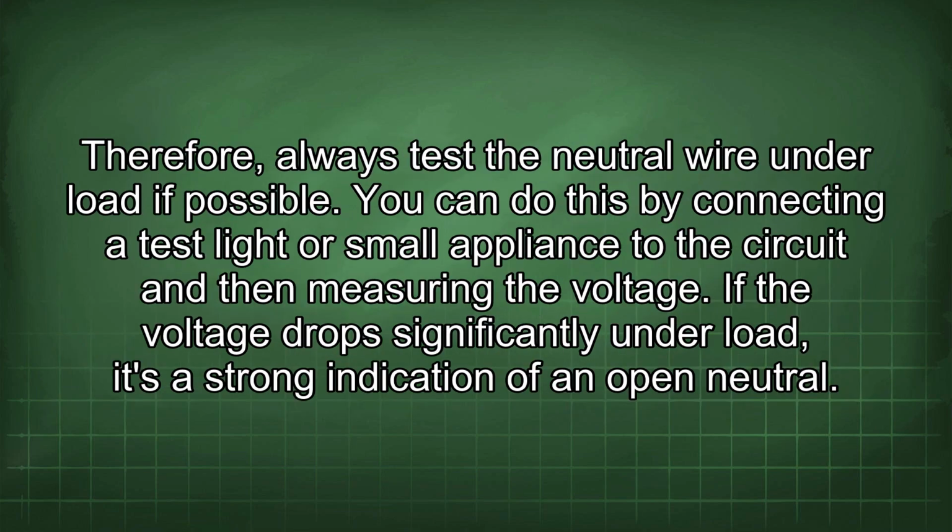Therefore, always test the neutral wire under load if possible. You can do this by connecting a test light or small appliance to the circuit and then measuring the voltage. If the voltage drops significantly under load, it's a strong indication of an open neutral.